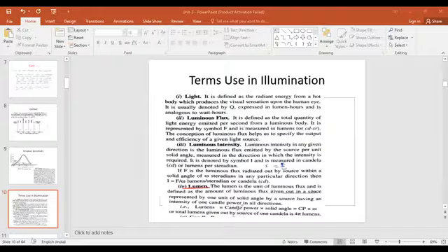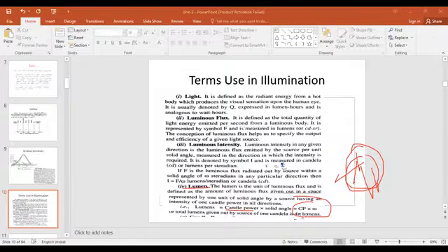Then again, we have discussed what the lumen is. So lumen is directly derived from this formula. When we derived this, lumen is equal to candle power, candela, here written as candle power, into solid angle. Okay. Lumen, candela into solid angle, CP W. Total lumen put out by the source in one candela is equal to 4π lumen. If any source emits energy in all directions, its three-dimensional solid angle is 4π. We will see this in detail when I explain solid angle. So lumen is equal to candle power into solid angle. We derive it from this formula.